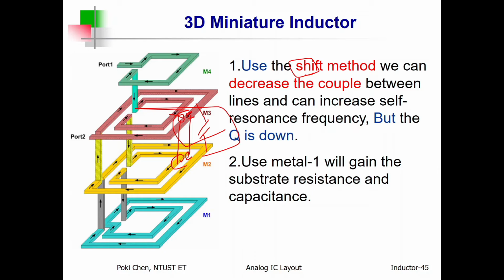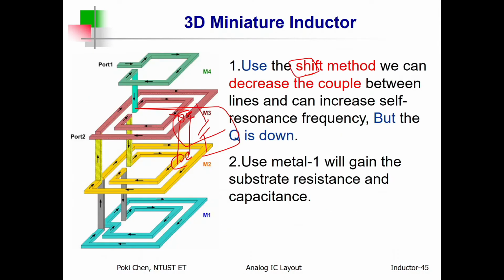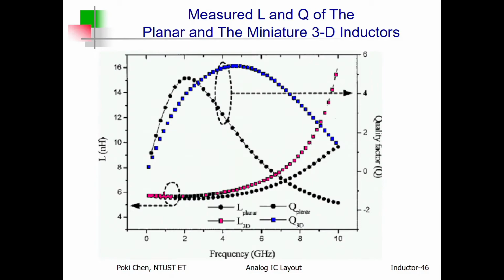Anyhow. Similarly, a stacked inductor, this one will increase the inductance very much, but the Q factor is expected to be lower. Nothing is free, you need to pay for it. So allow me to show you the measurement for L and Q between the traditional planar or spiral inductor and the newest miniature 3D inductor.